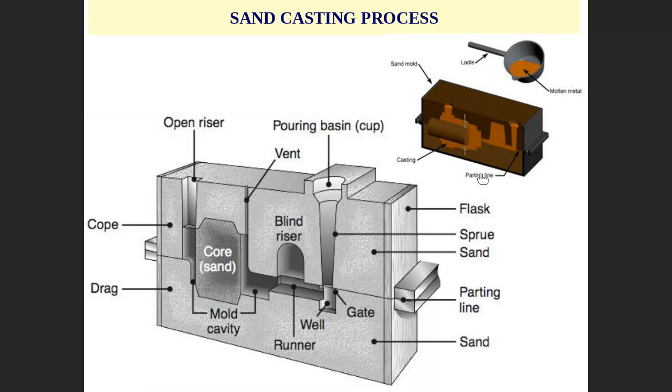Actually, it will happen. Listen to me carefully, we design the riser in a way to maintain the liquid for a longer time, to deliver liquid when the main part is frozen. In another way, the main part solidifies earlier, and this one solidifies later. So this riser will maintain liquid for a longer time. How come? That's what we're going to discuss in detail when we come to the design part.